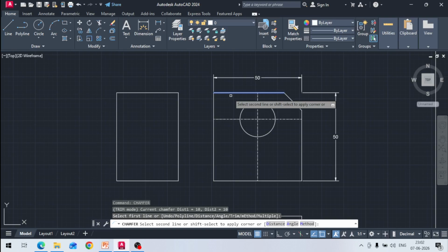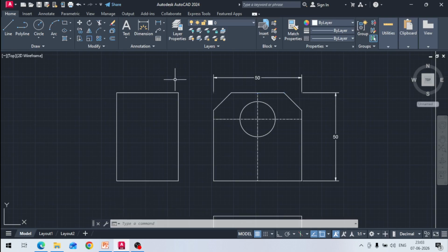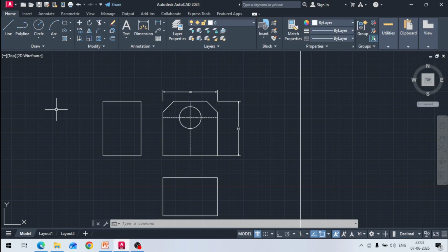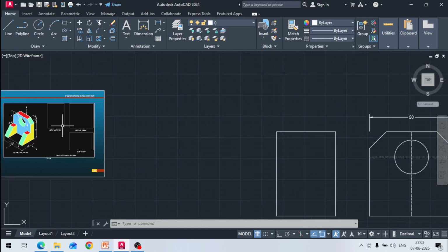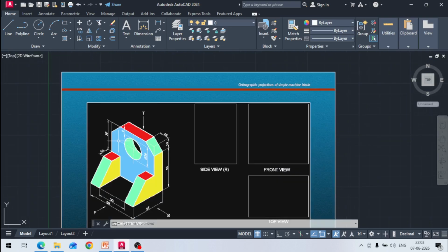Now what I have to do is, from the top at a distance of 30 mm. If you see here in this view, from the top it is 30 mm height. One line I have to draw like this, and then because this is 30 and 50, so 10 mm offset we have to do from both sides. Okay, from the top it is 30 mm.